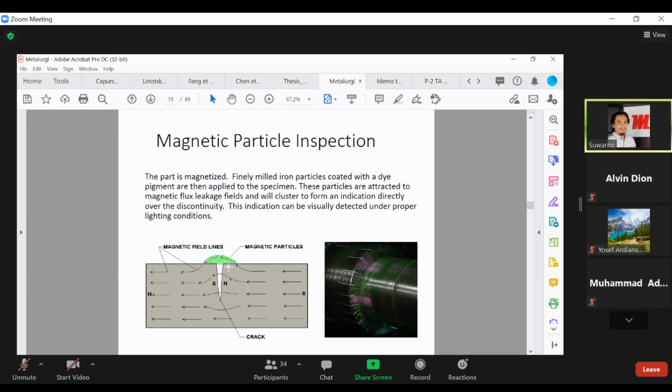So when we apply a powder on the surface, with its magnetic particles, for example iron oxide, and you apply a magnetic field using any other equipment, any tool to develop a magnetic field on the component, you see that there will be some disruption of the magnetic particles, and then it will be visible as a crack, like you see on the right side, because there is a change, a disruption in the magnetic flow from south to north. So basically, that's the thing.